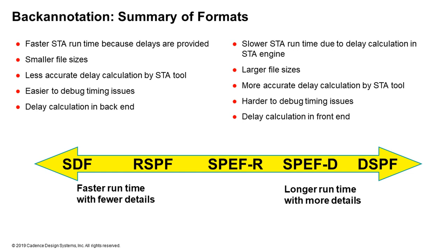You can start out with DSPF or SPEF and bring that information directly into your synthesis tool and let the synthesis tool do the delay calculation, or you can do the delay calculation ahead of time and then bring in an SDF. Either way, it all depends on what formats are being used and what the delay calculators are.